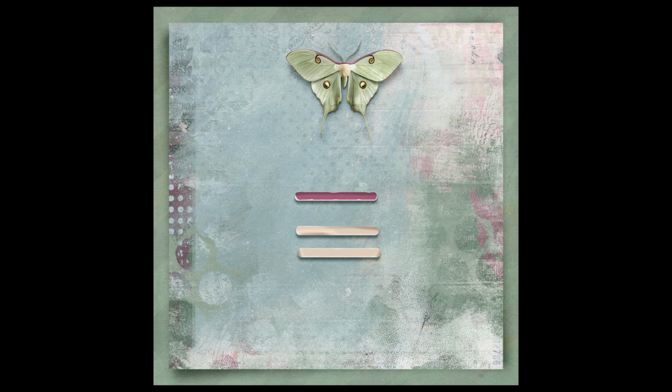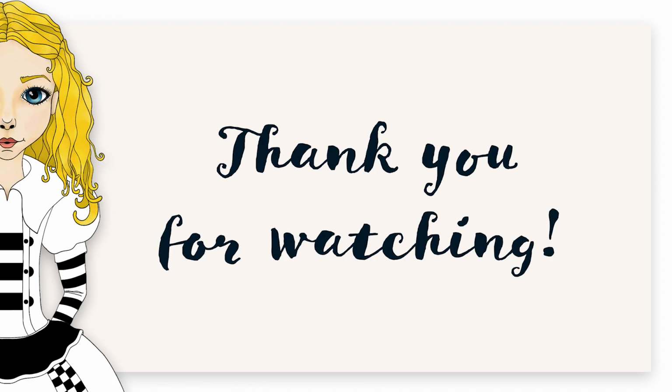As a recap, today I showed you how to lift the edges of your papers by using the warp tool on a shadow. I showed you how to create depth on elements by using shadows at 2 different distances. And I showed you how to use the burn and dodge tools on elements such as paper strips, which can cause them to have a crinkled, wrinkled look.